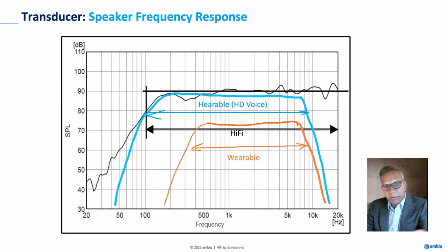So this is basically a frequency response. It comes straight from the standard. The standard provides the lower mask and upper mask. In terms of meeting these requirements, the standard specifies how the frequency response should look, what the loudness should be, and what the distortion should be. So what we are describing here is a brief intro on what we need to take into consideration when designing a telco device.